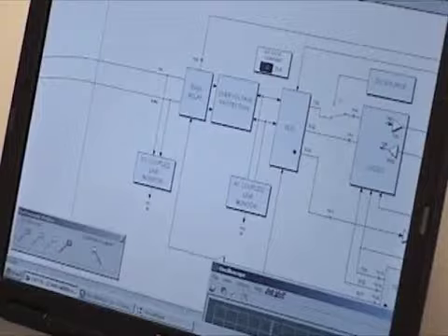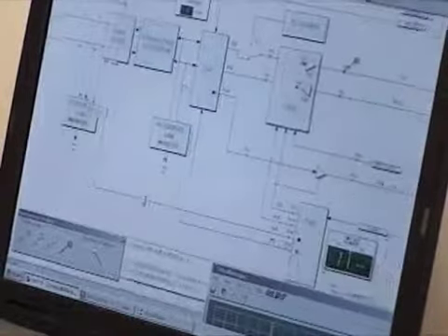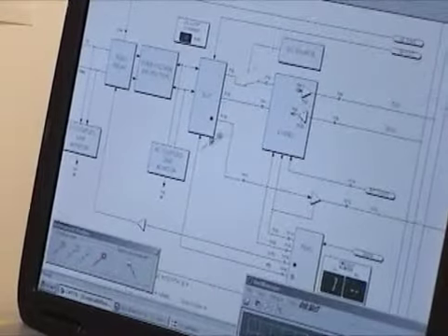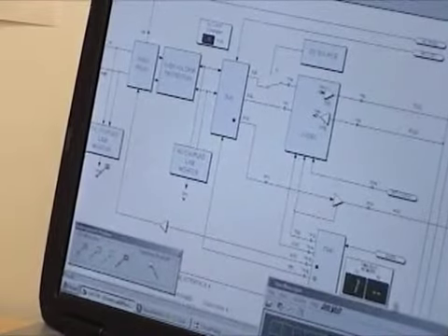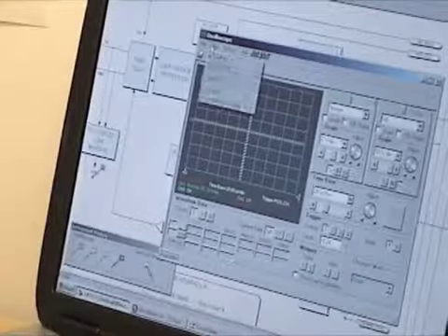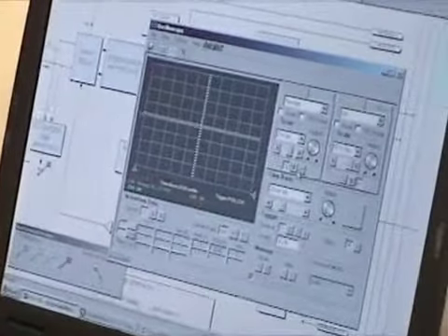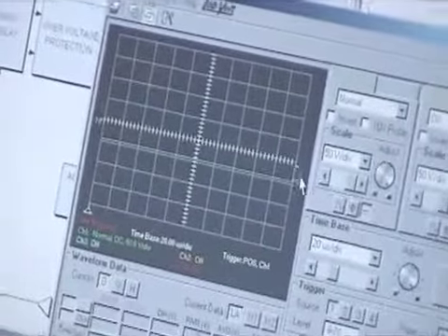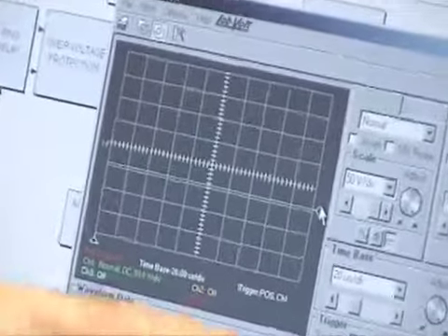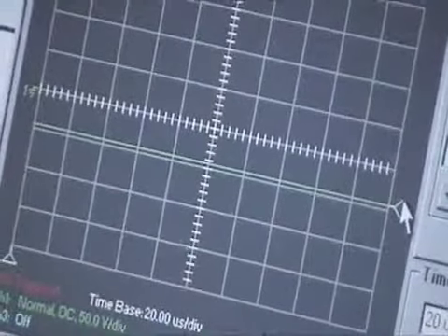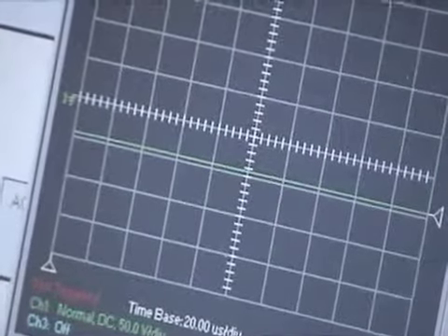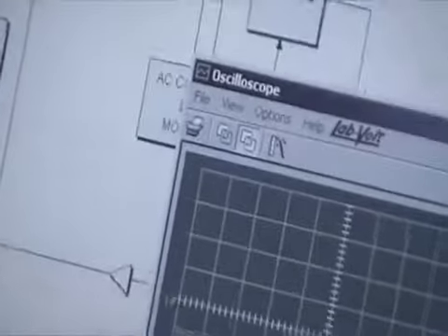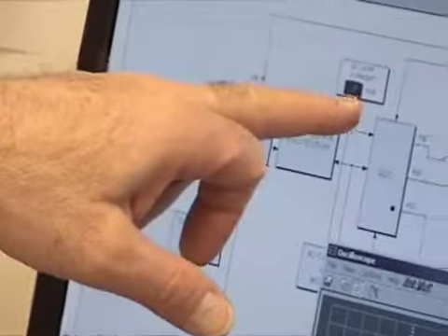the 48 volts. Now I've got to find one of the probes. There's the probe. So let me take the probe, and I'm going to put the probe over here. Okay, and then we're going to turn the scope on. Continuous refresh. I'm going to go to DC voltage. And there, what we can see is we've got about minus 48 volts sitting on this telephone line here. And that's what normally happens in a central office. It puts 48 volts on the telephone. Notice that there's no current drawn.